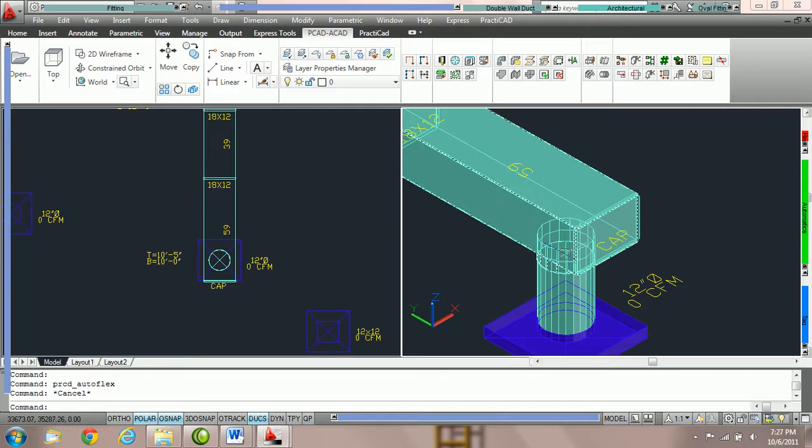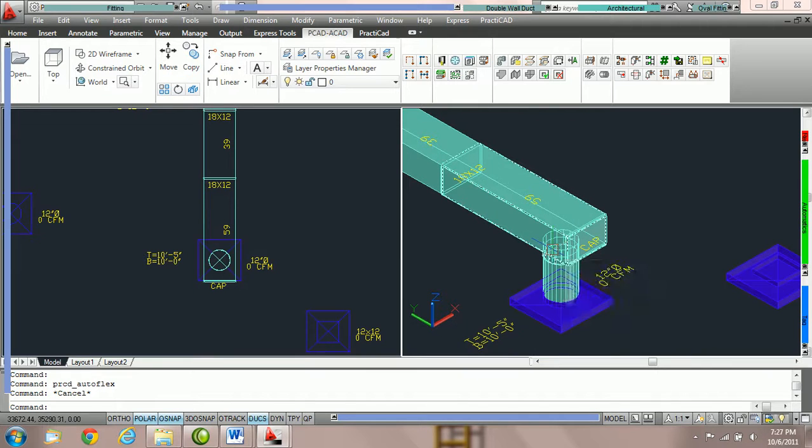The fitting right here where the cursor is, it's not highlighted, it's behind the fitting in the isometric, is the spin collar accessory directly from our catalog. So this is an example of why we'd want to use the spin collar accessory. It's for tapping to the bottom of duct that we are using to route to a grill.